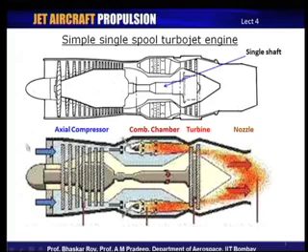So, the flow comes in through this intake system and gets into the compressor, and it gets compressed. And then after the compression process, it goes into the combustion chamber. Normally, between the compressor and the combustion chamber, as you would see here in the upper diagram, there is a small duct which is normally used to slow down the flow substantially, essentially to aid the combustion process.